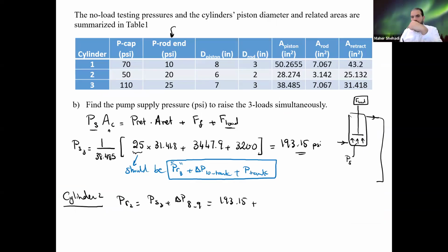If I'm moving forward, like if you have a pump pressure and you're trying to find the supply pressure, then you will need to remove that 5 psi from the upstream pressure. In this case, my upstream is PR2. So kind of like you will take the 5 to the other side to find this pressure and then move forward.